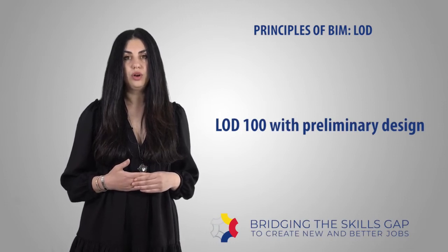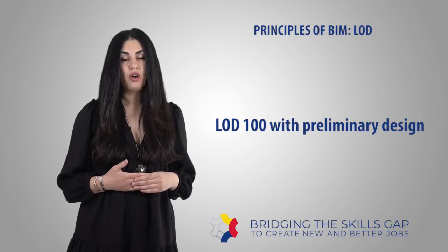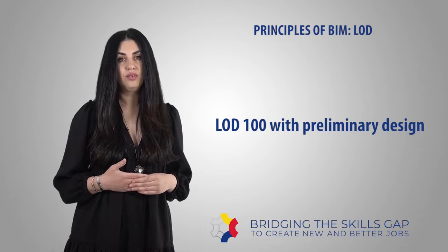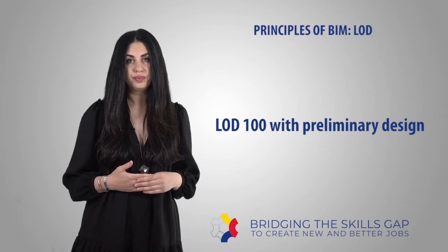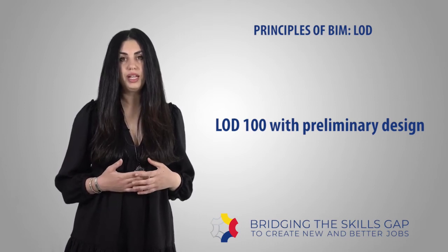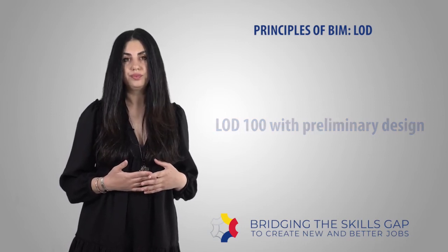LOD 100 is a concept design. The building 3D model is developed to represent the information on a basic level. Thereby, only conceptual model creation is possible in this stage. Parameters like area, height, volume, location, and orientation are defined. Let's take a look at this column. LOD 100 is a basic overall idea of the shape and no data. Just a box, which may be graphically represented in the model with a symbol.